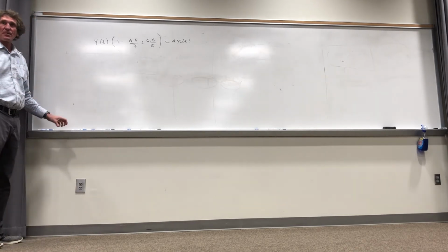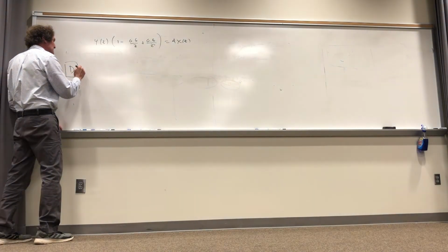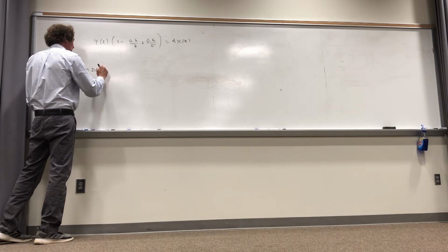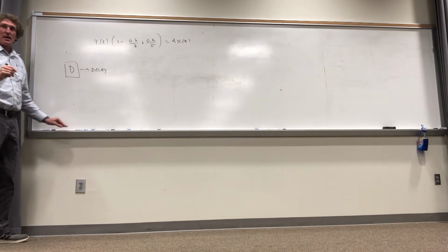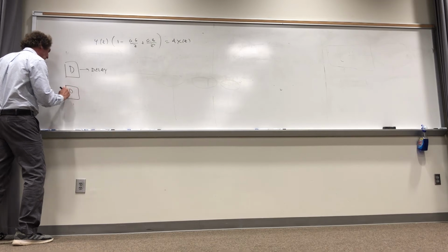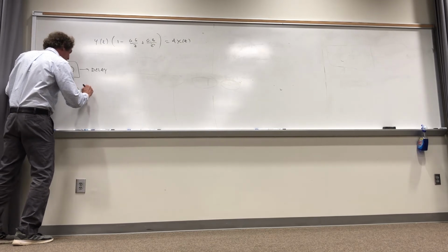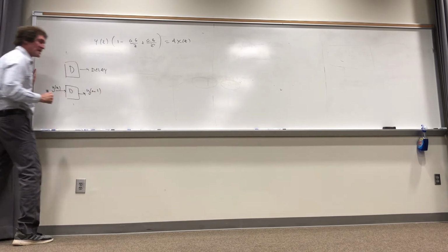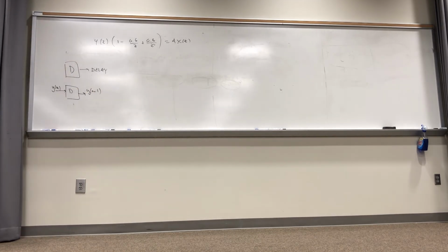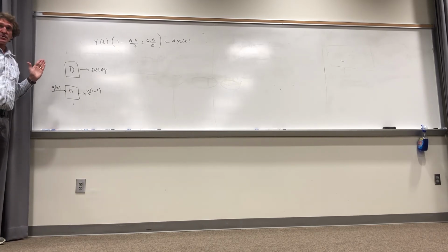Let me explain one thing. Anytime you see the D here, that is delay by 1. If you, for instance, had a delay operator here, and the input to that was y of n, the output would be y of n minus 1. It would delay the output by 1. Follow? That's the only thing a delay means. You'll see a capital D.